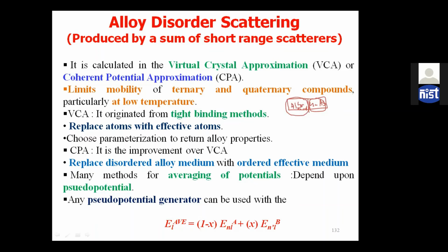However, you can take some other example. For example, if you take the electron gas which is essentially localized in the ternary alloy and weakly penetrates the barrier. If you take, for example, indium phosphide and gallium indium arsenide, then over indium phosphide you will grow this barrier, which will be indium phosphide. So you take the well, which is gallium indium arsenide, where you get the alloy. So here the electron is confined, the electron is here, and it can somehow also interact with the barrier.